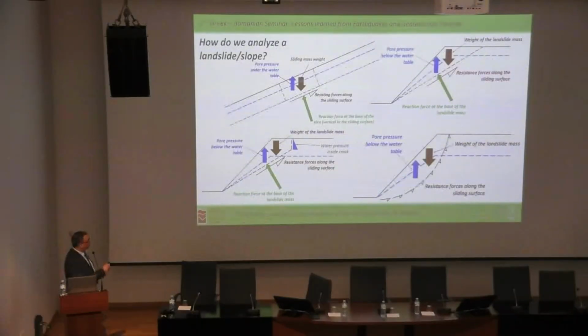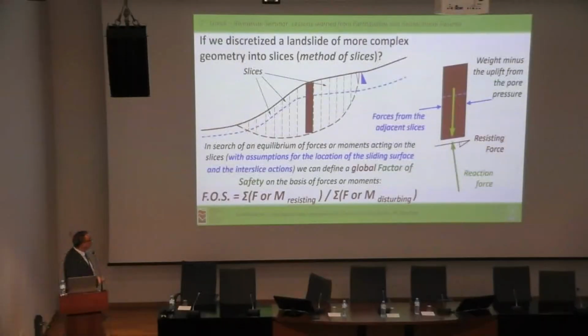We may have the infinite slope, we may have certain triangular or trapezoidal sliding blocks that we are considering, and we are trying to find the equilibrium, or even parts of circles where we could use simpler methods in order to analyze them with undrained shear strength and everything, or eventually use the slices method of limit equilibrium analysis, where we essentially cut in slices our sliding blocks